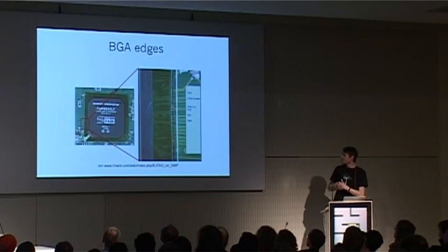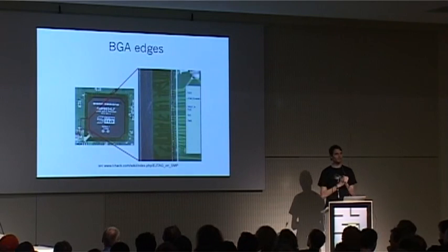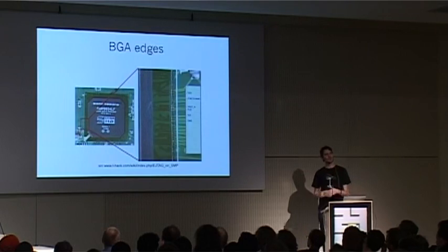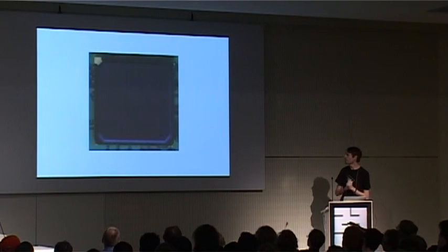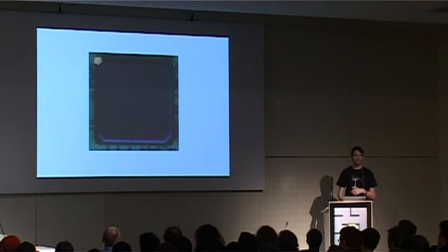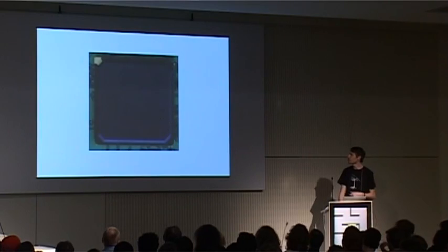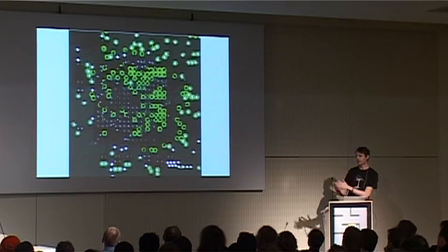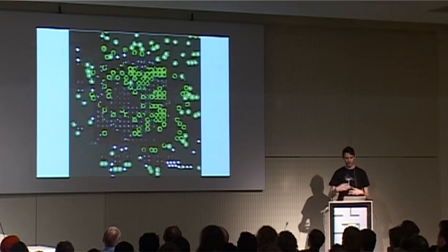But looking, I mean, this whole lecture I've discussed a lot of ghetto tools for looking at embedded devices. On the one hand, it might be nice to have really expensive and nice tools, but you find some very beautiful results when you use ghetto methods. In one case, I was desoldering a BGA chip, and I used a very horrible method. I just used a lighter because I was in a hurry and I wasn't at a lab. So I broke a lot of the solder pads, but using backlight behind the board, which I think looks great, I was able to try to remap them.